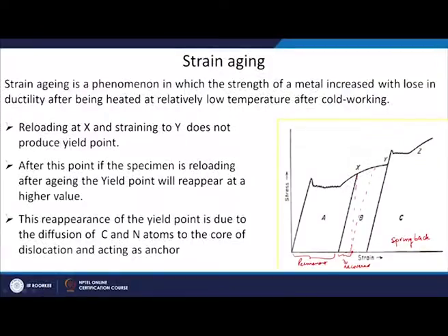Okay, this is just something I have rerouted here. Anyway, what we are doing here is, you have deformation past the upper yield point and then you started deforming under the strain hardening part, and you have stopped the deformation here and removed the load. Now, after stopping, you have again loaded the sample and started deforming it. So, you can see that it has started from the same point where you left.